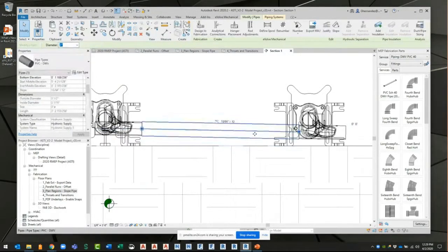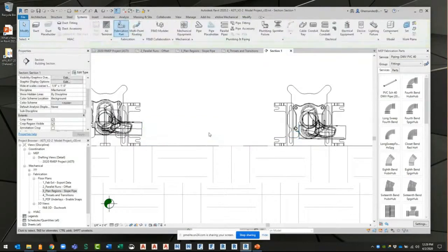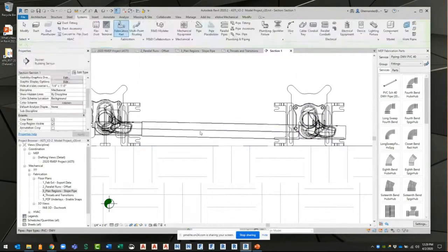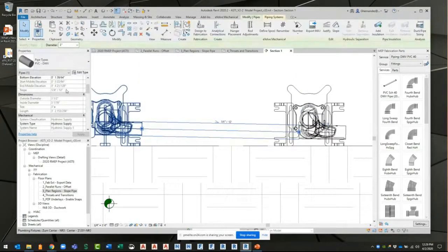But what I did was I just connected this 1/4 inch slope together now, right? But now look at the slope, how it's all jacked up. 15/64 over 12, right? So what we found to fix this was to just go ahead and delete it. Once you've worked out that distance, get rid of it with the proper slope, and then you can draw connector to connector, SX, to grab that connector, and it'll maintain that 1/4 inch slope.